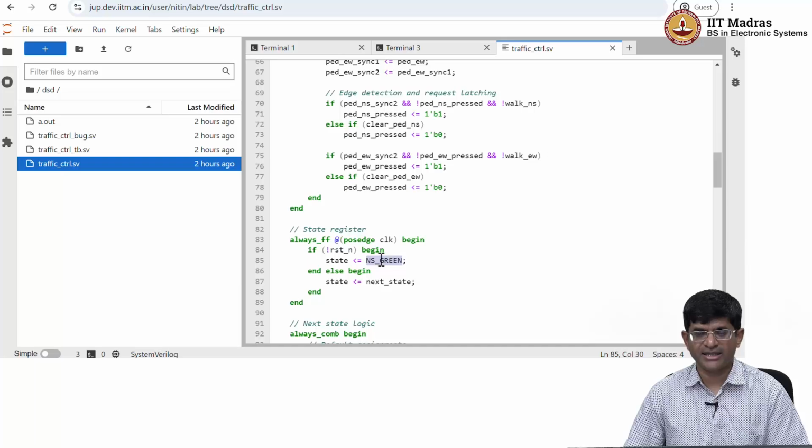Now the reason why in this case it probably is okay is that in any case when you have NS green, the rest of the logic also ensures that everything else is turned off, or there are no other signals. But you could argue that this was not a good decision. I am going to leave that. If you wanted to make sure that it was not a good decision, the simple way to do it is to modify your test bench so that it adds a check saying that after reset you should come up in all red. That's a nice way of specifying to the designer that you want the reset condition to be all red, because only by bringing it up in all red will they pass that test case. We will look at test cases in a moment.